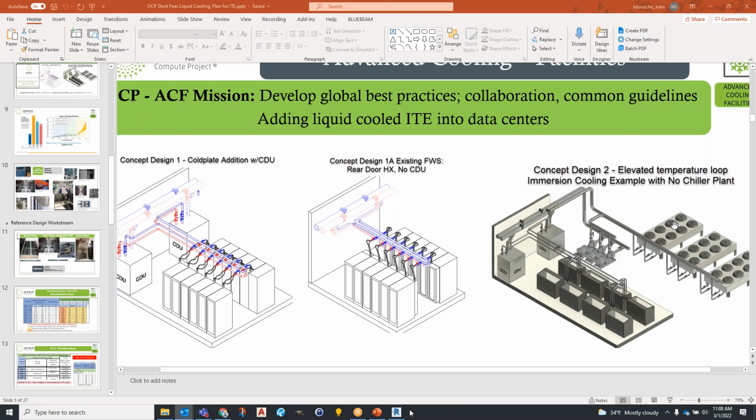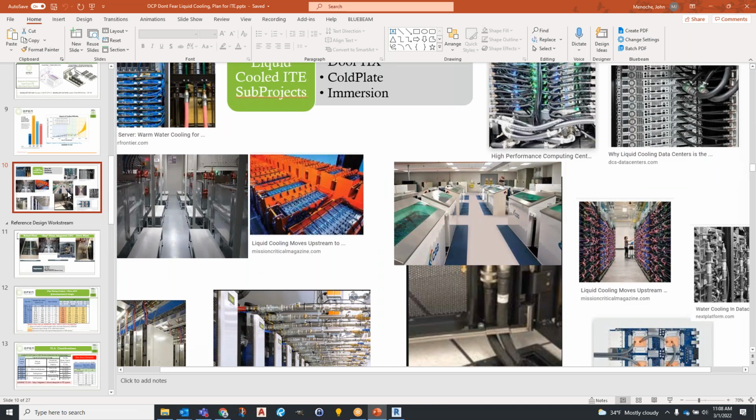The reason I wanted to bring that back up into the conversation is because if we lose sight of that when we're talking about facility floor design, one, we're going to end up with manufacturing floors for our floor structures. They're going to be seriously overbuilt. And we're basically going to sit here and tell folks that you can never put an immersion solution on the second floor of the building because nobody's ever going to design the second floor slab for 500 pounds a square foot.